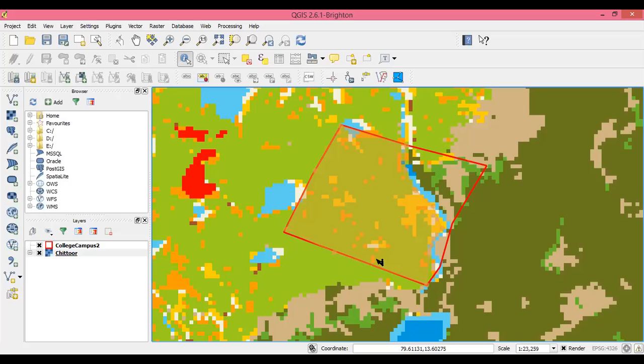So in this region, the runoff coefficient is going to change. The rest of the area, the runoff coefficient will remain almost undisturbed. Okay, so now you can assume that out of this 350 hectares, maybe 30% or 40% will get converted to built up area, right? So therefore, appropriately, you will compute the runoff coefficient. For the remaining portion, you will assign some runoff coefficient typically expected of some kind of barren land or agricultural land that has been left vacant.